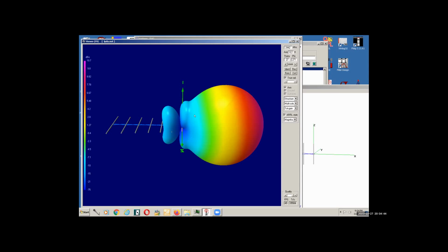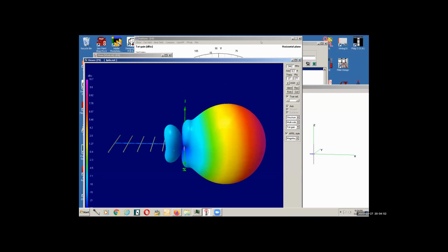Okay. And within the software package that you can download, is there something that allows you to independently define the models and then combine them together to get a field effect? Well, you actually build it as one file. So the 2 antennas would be in the same file. With 2 different sources and all the rest of it? Well, you really don't need to do the sources if you're just doing coupling. Well, if I have a 40 meter and a 20 meter antenna in the same field, those are separate excitations.